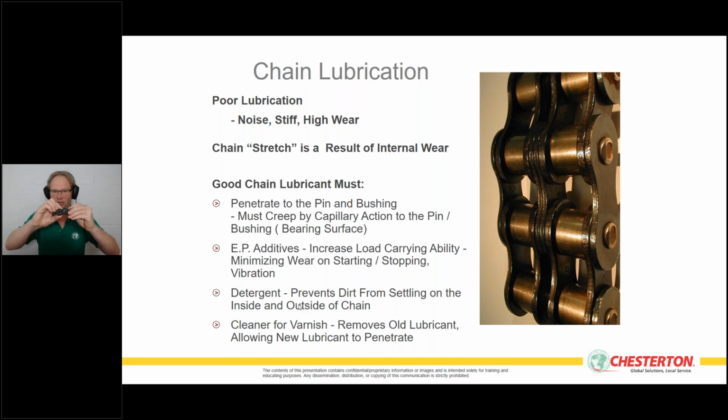If that gets into the chain, it will increase wear and tear. It will increase the friction of the chain. And when it increases friction of the chain, the same as with the sticky residue, it also increases power consumption, because the same engine, the same motor still needs to run the chain through it, and it has to work much harder to bend the chain to the right position to move over.